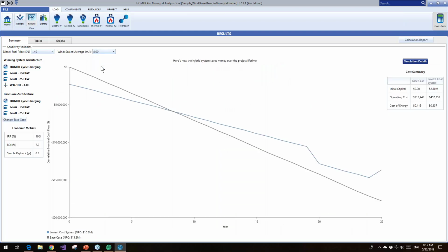And if you do, in HOMER Grid, it's relatively straightforward because you're generally connected to the utility, so you should always get some kind of results. If in HOMER Pro you get infeasible results, I'd recommend adding an auto-sized generator, checking what kind of renewable fraction constraints you've set. There's several different ways that we could end up with infeasible solutions, which basically means that the generation sources that you've defined with the constraints are not meeting your load. So if you're getting that and you're frustrated, we have help resources. Of course, we're willing to help you through that.